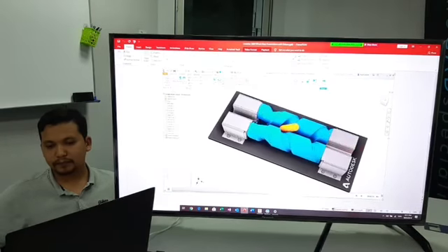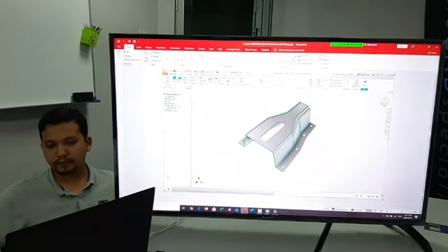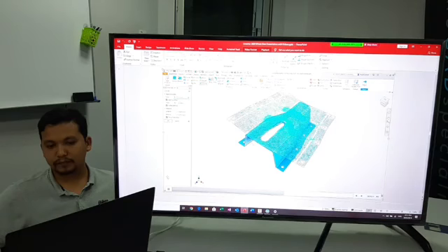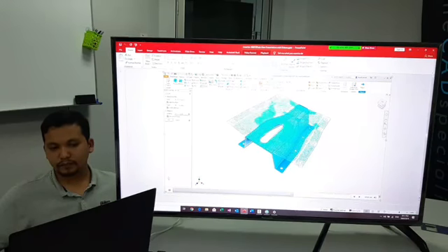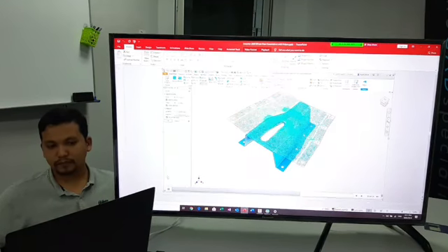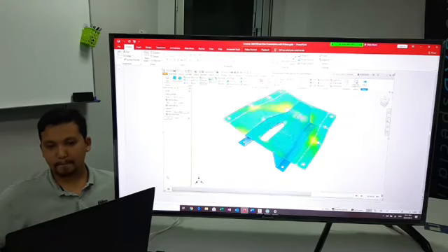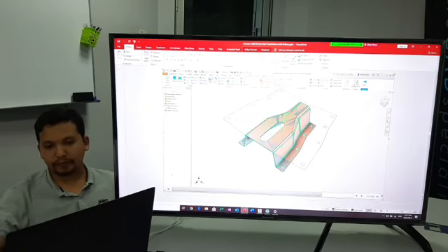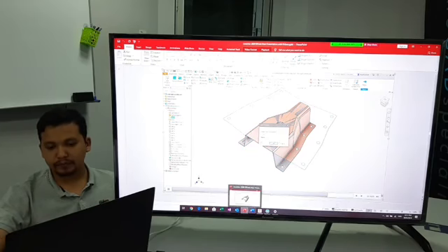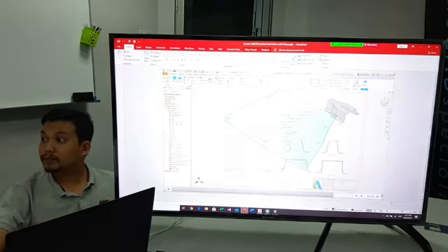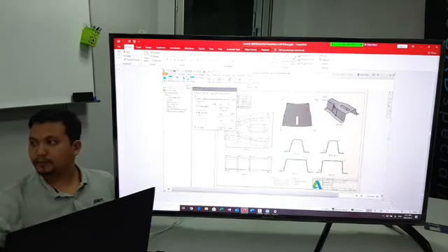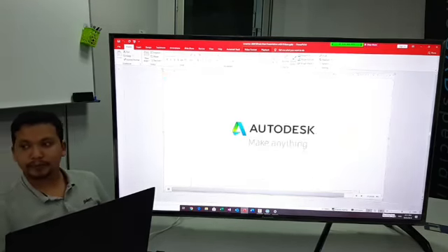To help create flat shapes from complex surfaces, Inventor 2020 introduces a brand new unwrap command. This allows you to get a flat shape from any set of continuous faces. If a face can't be calculated with the unfold command in the sheet metal environment, flatten it with unwrap. During the unwrap process, a heat map shows areas of highest to lowest tension. Specify segments to remain linear, for example, keep an edge straight or rigid, or keep a hole round. Plus, it's easy to isolate and document the output surface with an option to create a dedicated view representation. Check out these enhancements and more in Autodesk Inventor 2020.